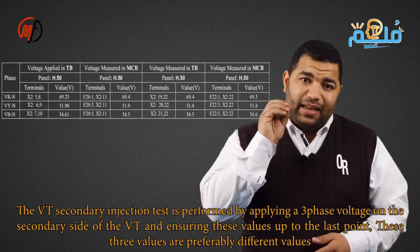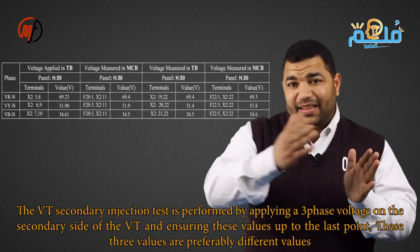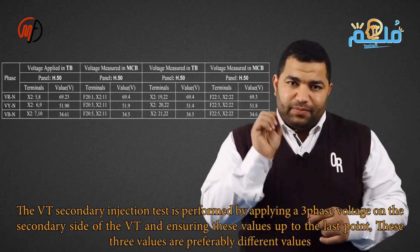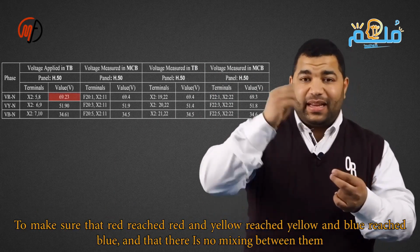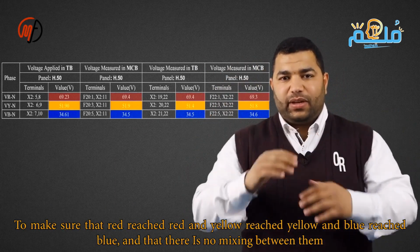The VT secondary injection test is conducted by applying a three-phase voltage to the secondary side of the VT and checking these values all the way to the last point. It's preferable that these three values are different to ensure that the red is connected to the red, the yellow to the yellow, and the blue to the blue with no mixing between them.